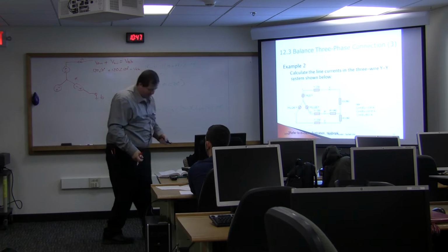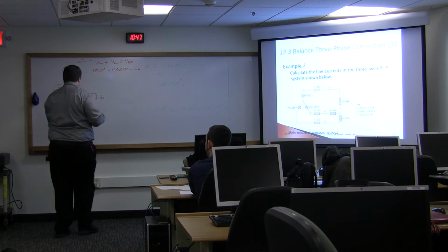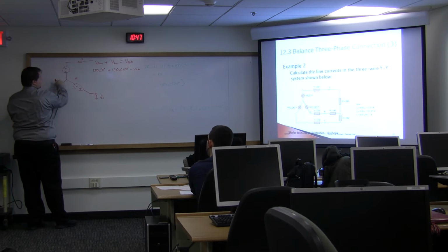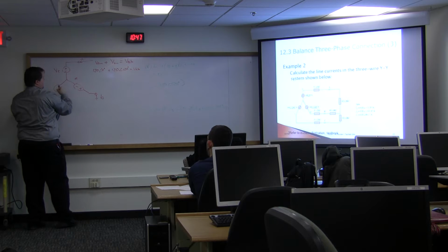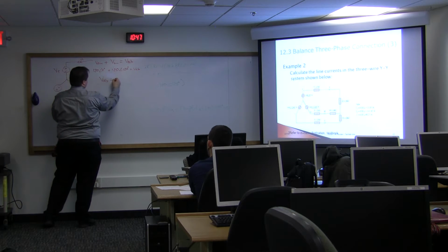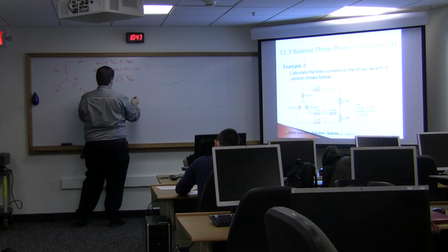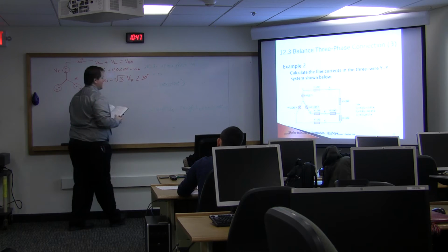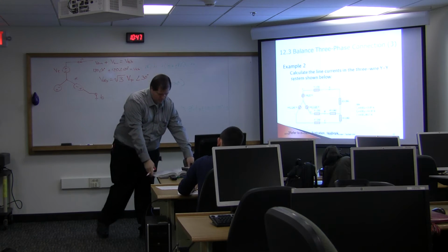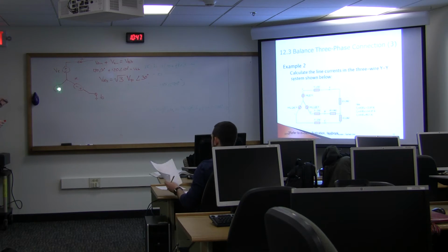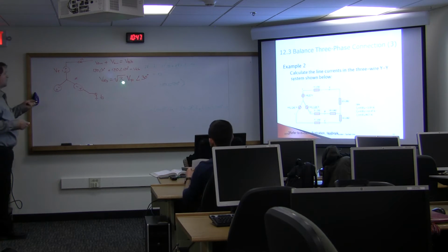And it actually ends up being, they have it all worked out, like I said, in the book, on page 510, if you want to look at it exactly. But it ends up being that whatever this phase voltage is, just the magnitude of this, that's VP, it ends up that VAB equals root 3 VP with a phase angle of 30 degrees. The other ones end up being 120 degrees out of phase with this, but all with a magnitude of root 3 VP.